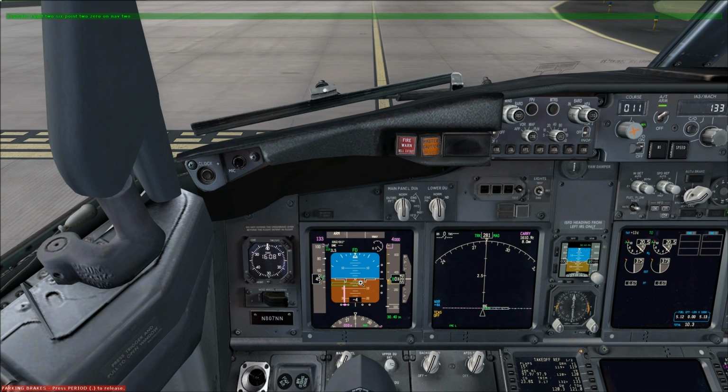It states that in steady state flight conditions below 1000 AGL, if any of the following is in excess: more than 15 knots indicated airspeed change, more than 500 feet per minute vertical speed rate of change, a change in pitch attitude of more than 5 degrees, or 1 dot displacement from glide slope or more, or any unusual thrust lever position for a significant period of time, then you're probably experiencing windshear.